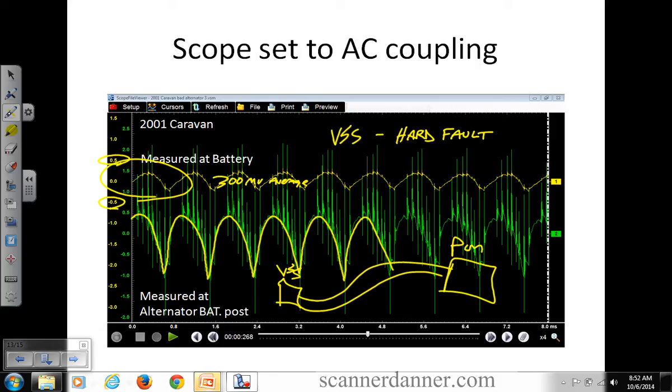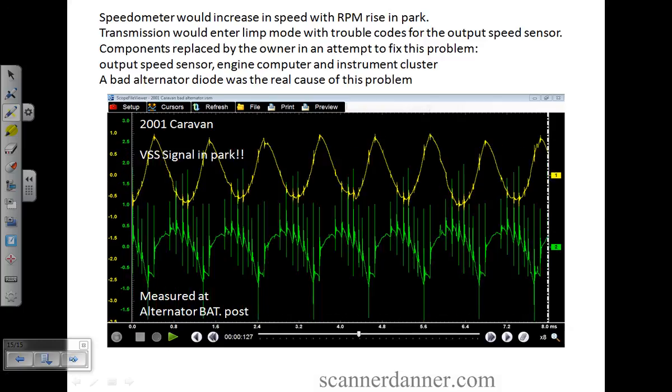So this is where I get the car. I decided to actually, I'll walk through this whole thing. I started at the vehicle speed sensor. In this particular system, it is a 2-wire sensor. This is significant. Why did this affect the vehicle speed sensor circuit the way it did? The vehicle speed sensor on this particular car makes an AC sine wave. It makes its own voltage.